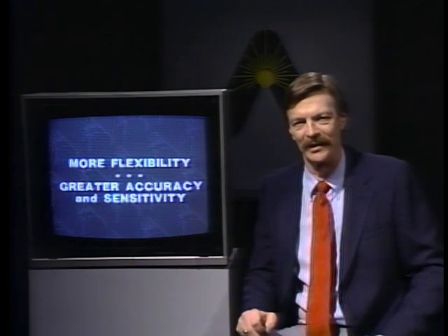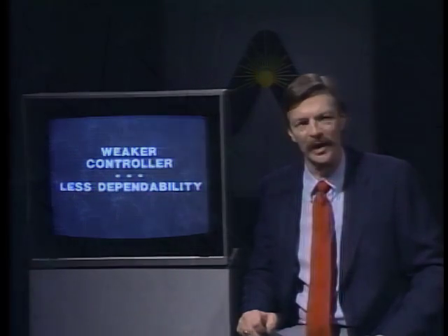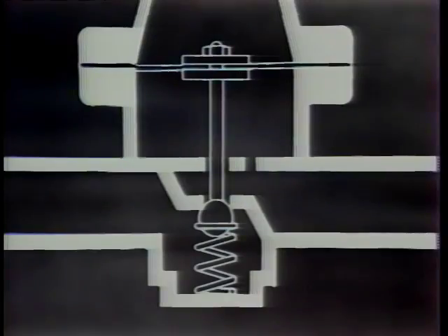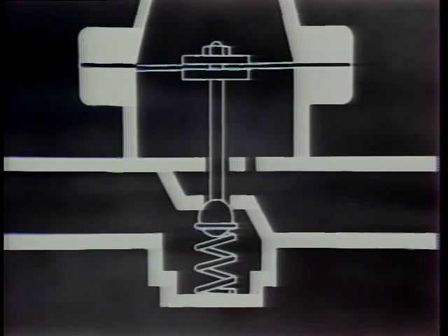And finally, a limiting factor is placed on the PRV by the fragility of the controller. It bears the total differential pressure between the outlet chamber and atmospheric, so more flexible but weaker controllers may be damaged by high pressures. The simplest controller is a flat diaphragm. While inexpensive, this type of controller is limited in flexibility and travel. Diaphragm controllers are used in low pressure and flow situations where neither sensitivity nor accuracy is of much consequence.